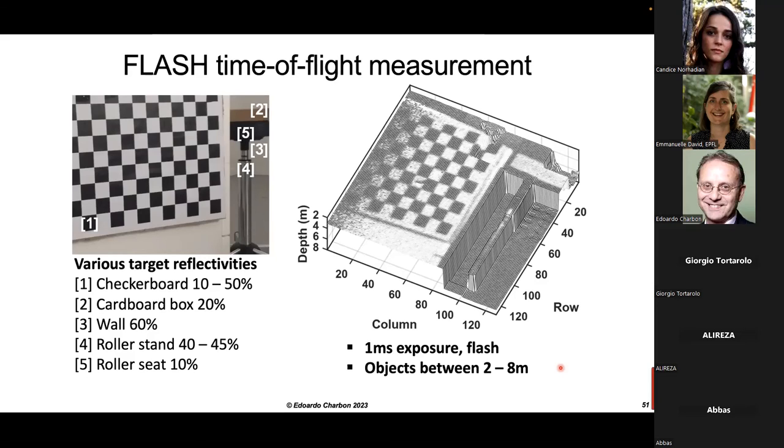Yes, I should have added the slides, indeed. We've done extensive characterization of SPADs for ESA. So that included gamma radiation up to 3 megarad, proton irradiation at 2 different energies, 11 MeV and 60 MeV, positrons, electrons, and even X-rays.